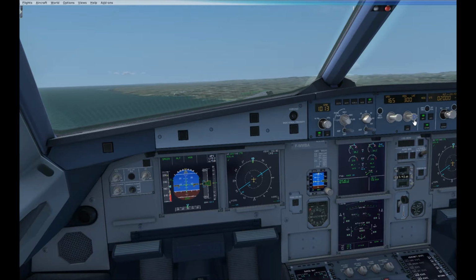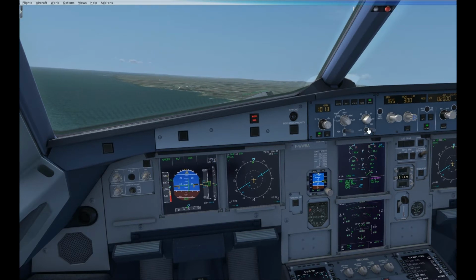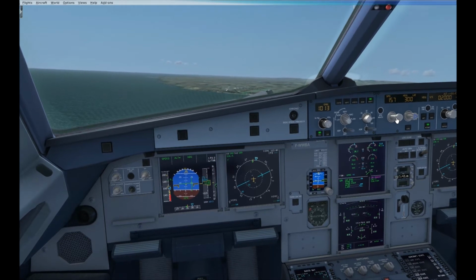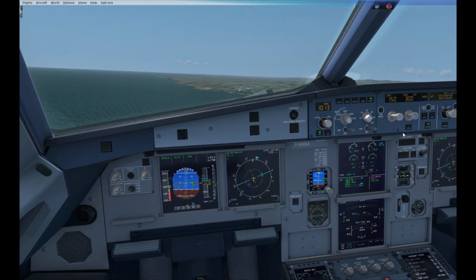Alright, autopilot off. We're now going to manually fly the aircraft to the ground. The warning is telling me the autopilot is off. I will cancel that warning. Make the turn to the runway. Reduce my speed to 150 for landing. Increase my flaps. Gear down.